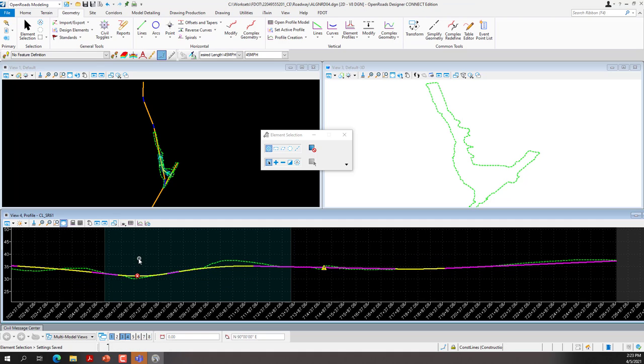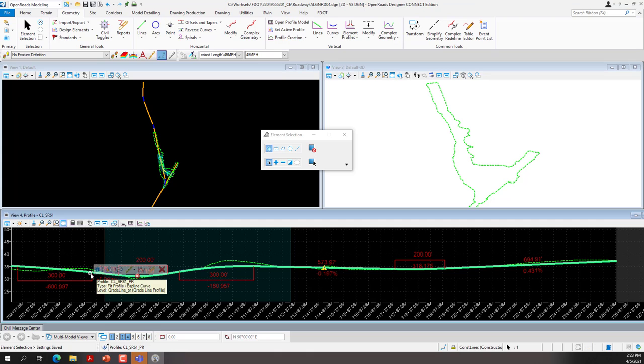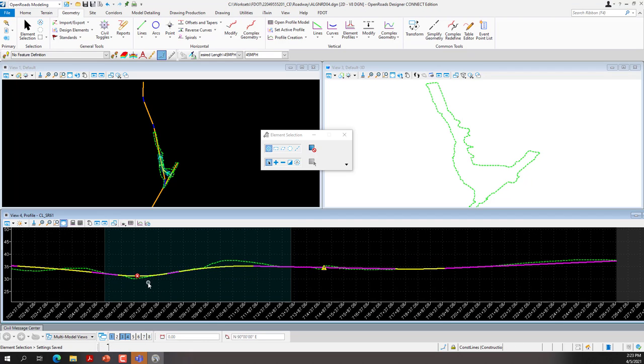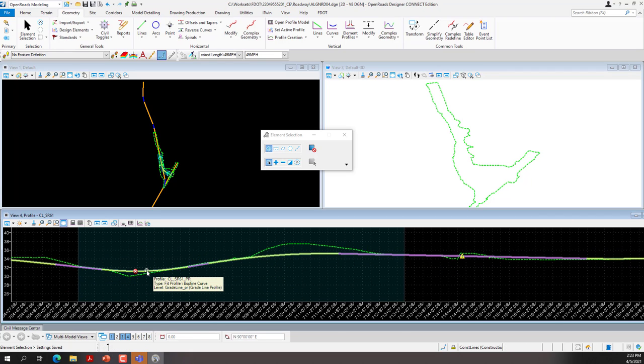So if I deselect it and reselect it again, like we did in previous exercises, what we'll need to do is select and then right-click. Now this tool is going to work a little bit different, because we can't edit these. But to fix these, we'll need to select the profile, and then come to the fifth icon over, Convert to Profile Rule, and click on that. That'll make these editable. So now we can edit this profile.